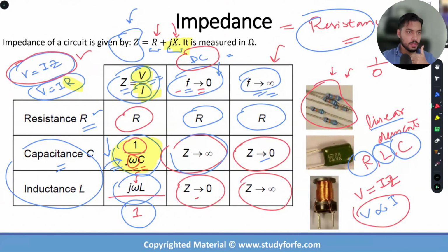So your resistors, it's also a good interview question. You get asked on an interview, give me examples of some linear elements, right? You'd be like, yeah, I know 3 linear elements, resistors, inductors, and capacitors. Follow-up question, why are they linear elements? Because they hold the linearity for Ohm's law. Okay, can you explain? Sure, V is equal to IZ. You see this proportionality sign? When you turn it into equality sign, the thing that remains constant is Z. And this Z can take the form of resistor, can take the form of capacitor, can take the form of inductor.